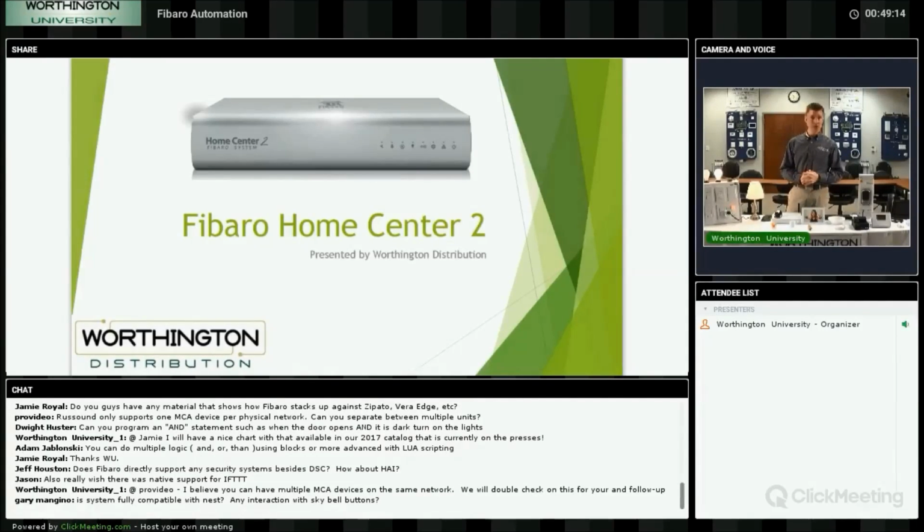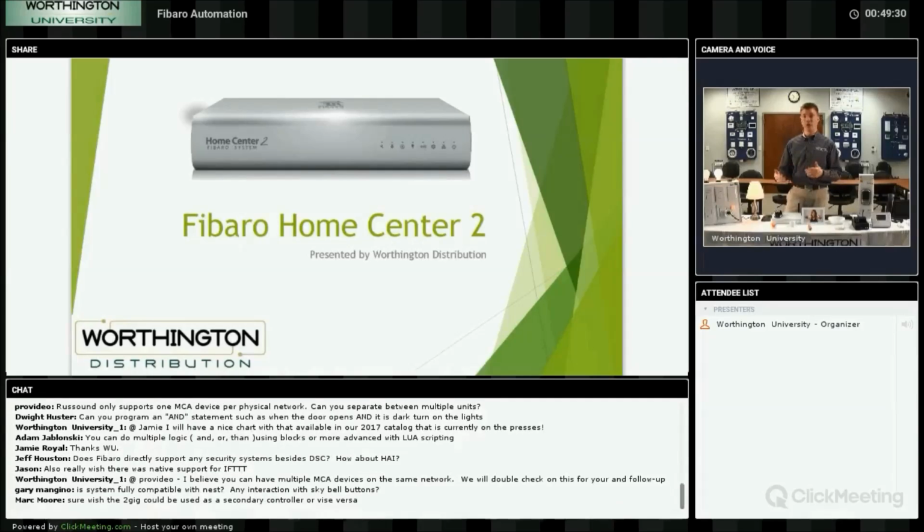There's a question on 4-button controllers. They do learn into the system, and you can use them. What you want to watch out for, which gets a little bit weird, is the LED on there. The LED on the 4-button controller typically shows you the status of that scene. So if that scene is true, meaning all the lights in it are on or meet the scene criteria, that light's going to come on. If they're all off, it's going to be off. It doesn't really work that way in here because we're using it more in a generic sense rather than in that VisRF terminology. So yes, it will learn in, and you can initiate scenes from it, just that the LED status won't always be true.